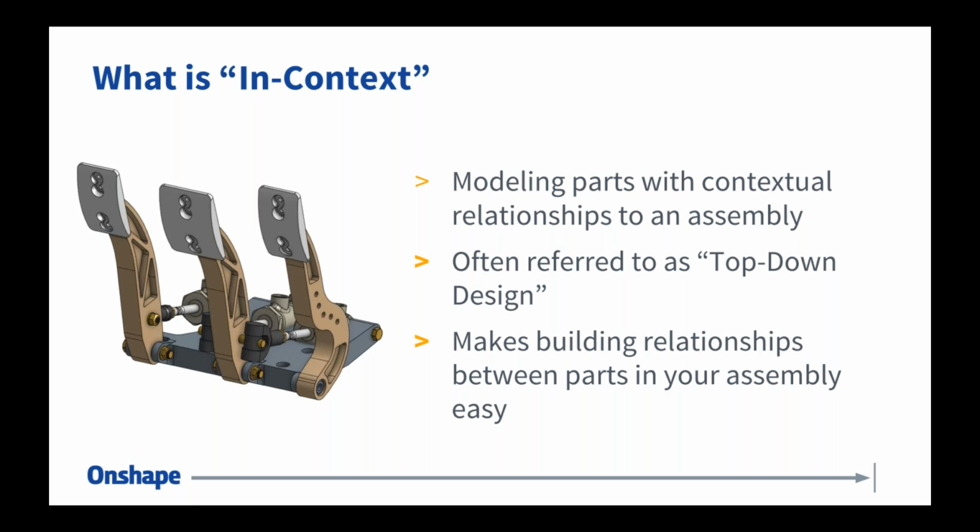If you're positioning a lot of parts, that's a big indicator you should go to in-context. If the motion of your design is critical to the design itself, and not just like in the pneumatic cylinder, which has motion but it's just a simple in and out. If I'm building features around all these positions, and at a certain point I need to have a stop at this angle relative to this position of the assembly, that's where in-context really comes in. When we start talking about, at this position I need this, and at this position I need that, and I need to accommodate for this at this certain orientation, that's where it becomes really advantageous.